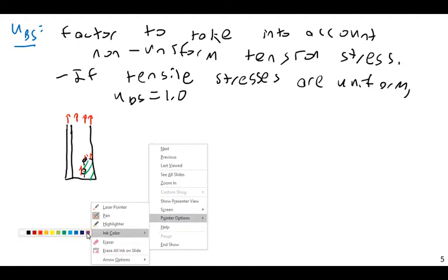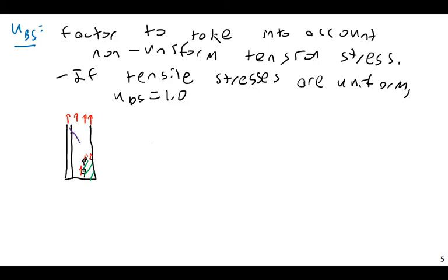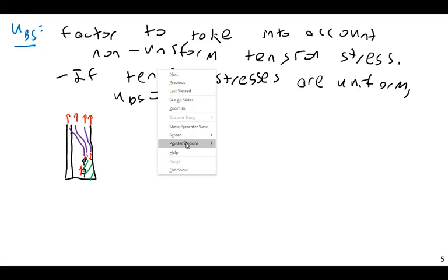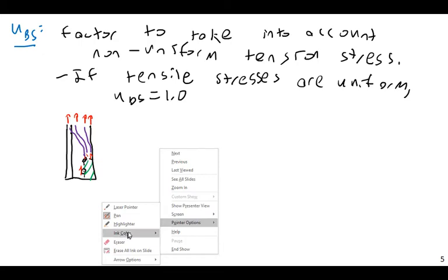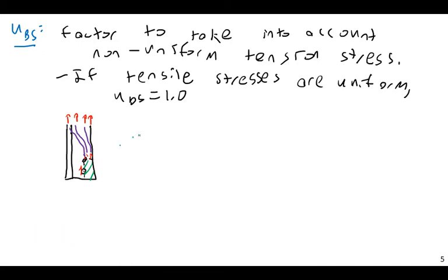So effectively, you're going to get a great deal of stress concentration. All this tensile load has to end up concentrated down here. We get stress concentrations. So, in other words, if we look at just the tensile plane of the shear block, if we zoom in on this thing here, stresses on the tensile plane of our shear rupture block, stresses on the shear plane of the rupture block.